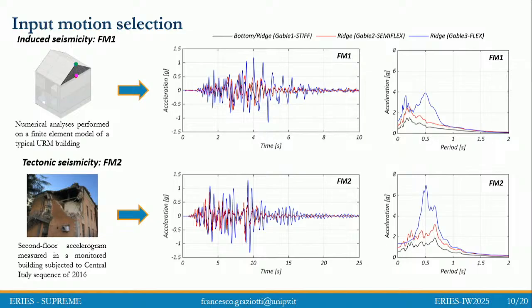And we actually succeeded in having the accelerograms assigned to the two tables, with pretty decent smooth spectra, because you also have to consider that in this type of test it is always much better to have something relatively smooth in terms of spectral acceleration, in order to study the actual behavior in a more robust way. Also, if you want to reproduce it numerically.